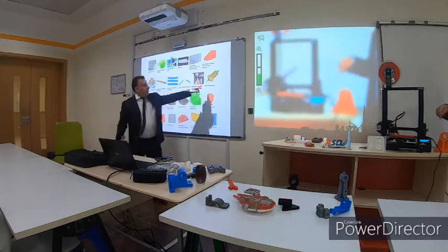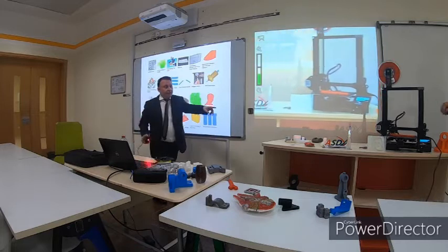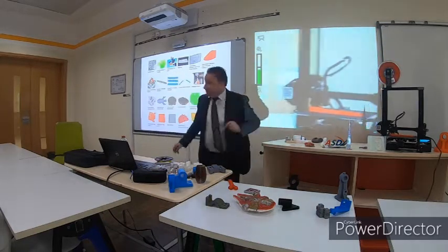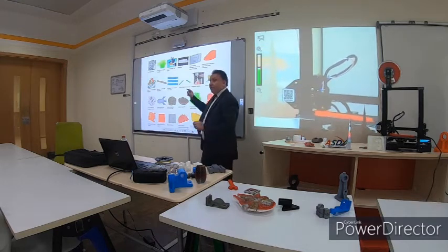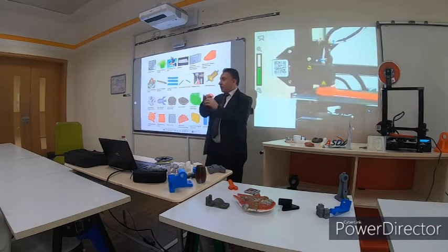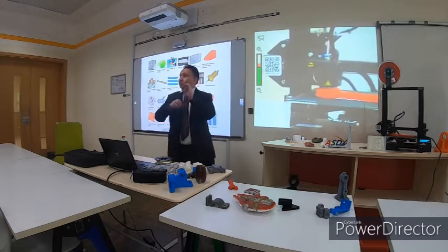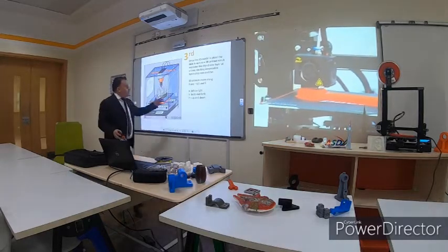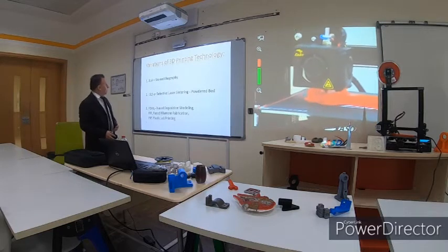Also, these are other types of errors. Sometimes you need to change the nozzle. This one comes with three small nozzles. Can you see the brass one? It's underneath this one. Sometimes it's clogged or blocked, so you need to unscrew and remove it. So as we said, after that we send it to the printer.